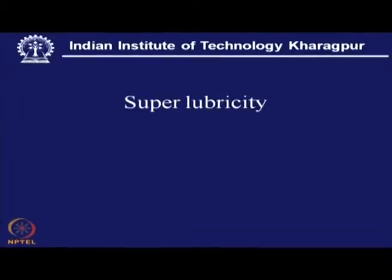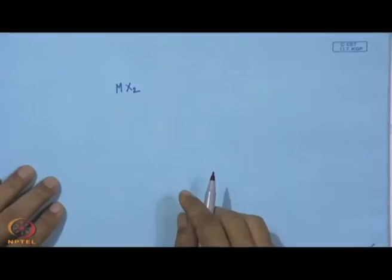Sputter deposition of molybdenum disulphide coating. Now, this molybdenum disulphide or say tungsten disulphide, these are the materials which we can put in the form of this formula MX2, where this M stands for one element of this transition group, and these sulphides are known to have a very low coefficient of friction, or in other words a super lubricity.